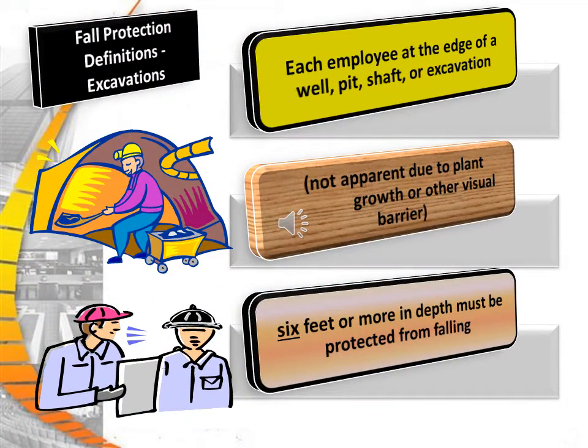Each employee on the edge of a well, pit, shaft, or excavation 6 feet or more in depth must be protected from falling.